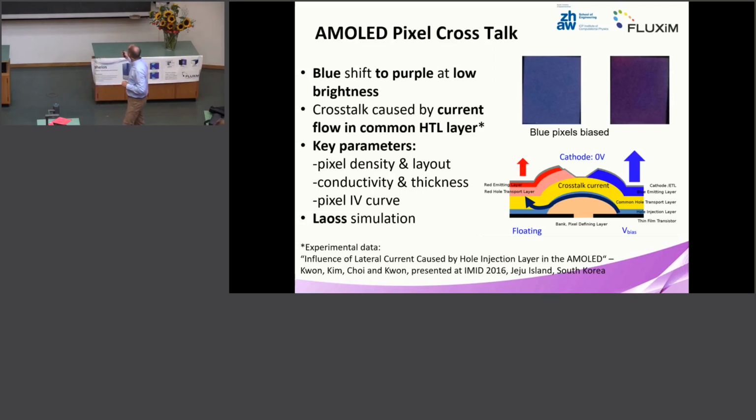So what is happening here, a typical cross-section of an OLED display, we have here an anode from this top emission OLED of the blue pixel, and an anode for the red top emitting OLED pixel. And some of the layers are uniform across several, or actually all pixels.